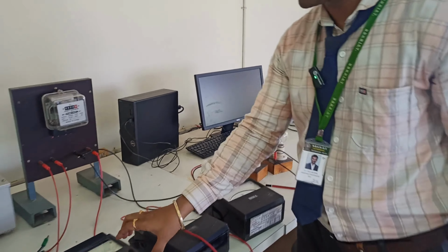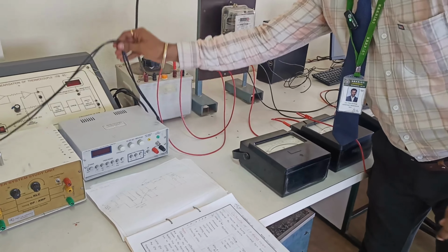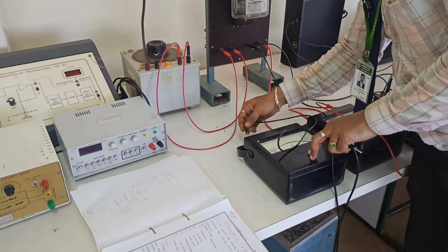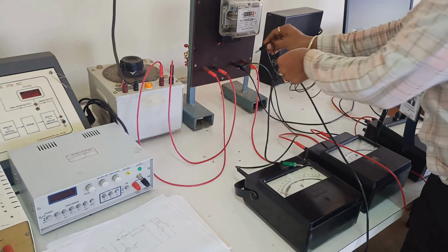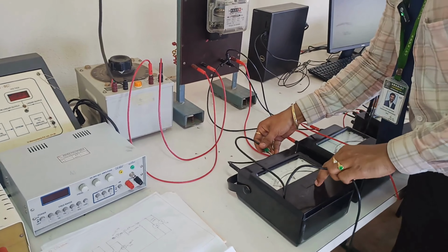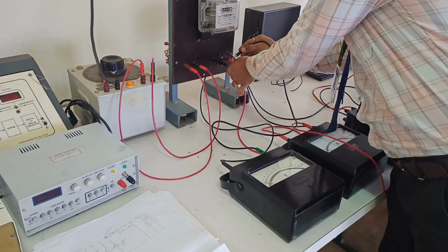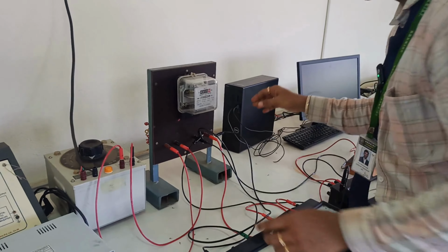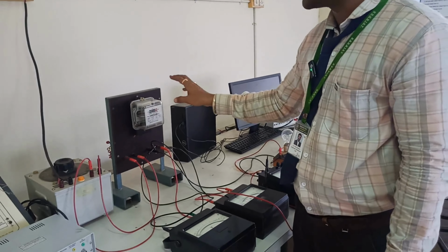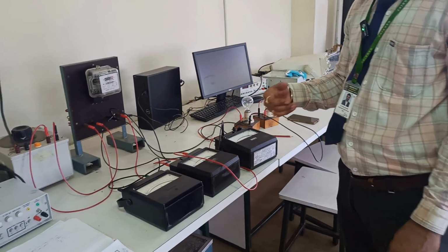Now the last one, we have to connect the voltmeter. Okay. So to connect the voltmeter we are going to have two wires. So connect the negative to the negative and positive to the positive. Okay. So this is the phase and connect it to the positive. Now this experiment will help us to calibrate the energy consumed by the watt hour meter and the error developed by it. Okay. Now we'll proceed with the experiment in the upcoming video.